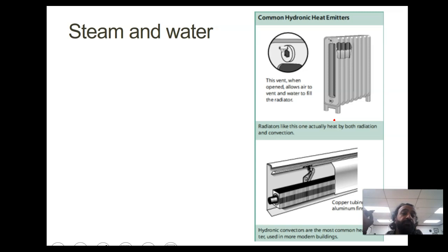Steam and water, that's what we call hydronic. So we can heat steam and send steam to radiators, or you can heat water and send the water through small finned radiators, and they both are very quiet. We're heating water or steam, and the steam or water will interact with the radiator. This will get hot, and these heated fins will eventually heat the air, and it is natural convection because the air gets heated and rises by itself and drops again when it cools.